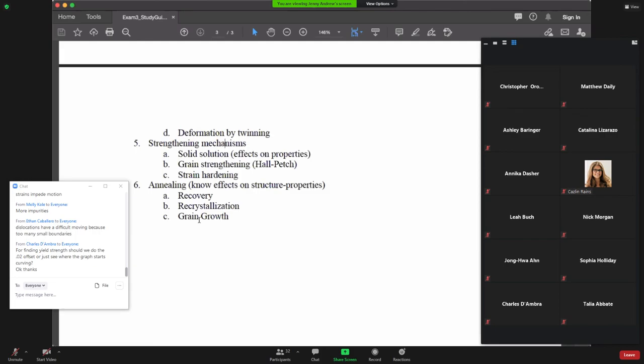Other questions? Jason, you unmuted, I think. Yeah, I had a question about the frequency effects on the polarization. If you were to graph frequency against polarization and you had a material that exhibited a bunch of them, like all four, or maybe just three or two, would you see sharp drop-offs at different frequencies, or would you see pretty consistent behavior? No, it's more a sharp drop. It almost looks like a step. And I think there was a slide on that back in the electronic properties. But yeah, it's orders of magnitude that drop off as you transition between them. All right, thank you. Yeah, no problem.